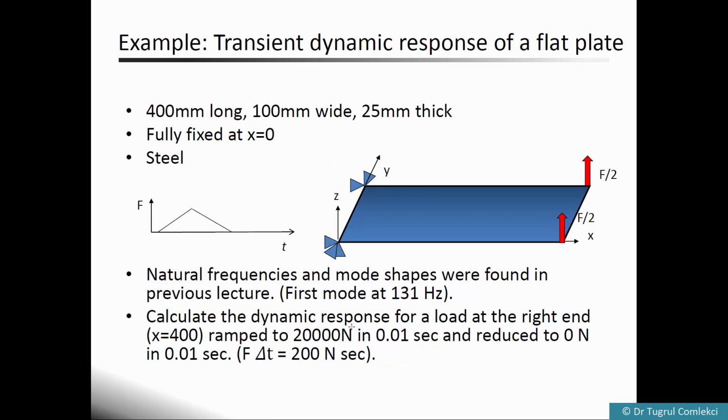Following the modal analysis, we'll look at a transient dynamic response of this plate, and we'll apply a force on the right edge so that it goes up to 20,000 newtons in 10 milliseconds and goes down again to 0 in 10 milliseconds. It's a ramped load, almost like an impulse loading on the right, and we'll look at how that will affect the response of the plate.